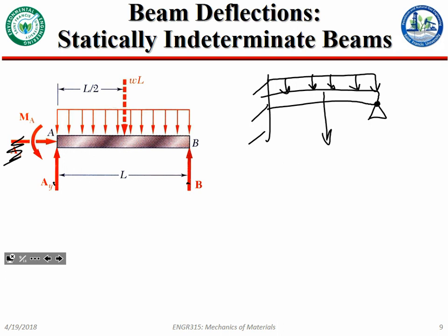Oh wait, sorry, that's actually not there. The dotted arrow in the middle is just a representation of the distributed load. How you can treat that load as one concentrated load of the same magnitude at the center of the distribution. Remember that fun thing? They're just saying, hey, you can do that.